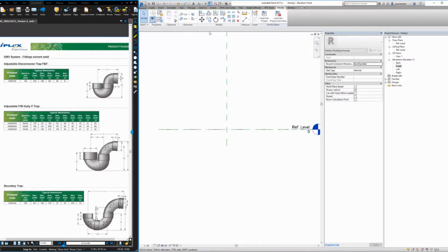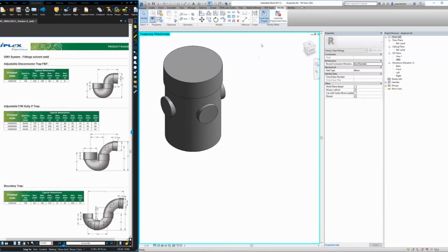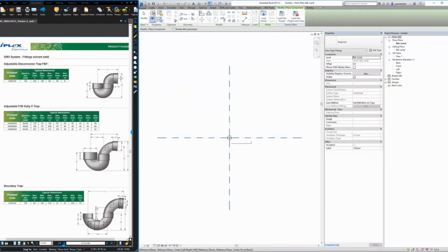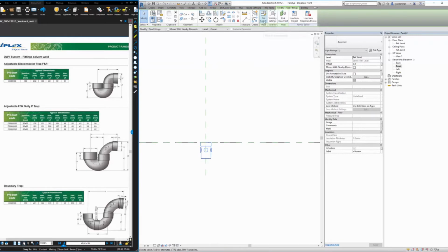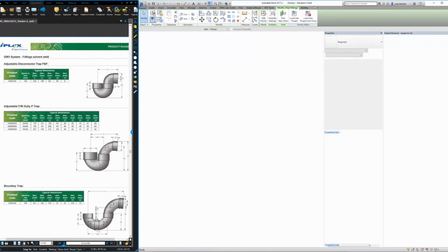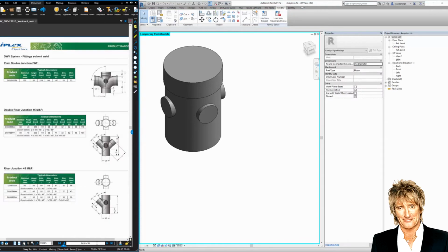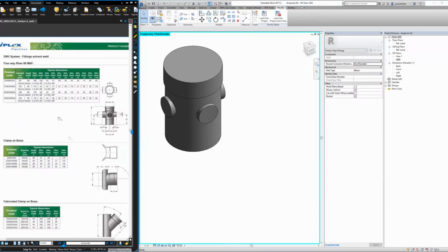So hydraulic designers out there would know that people stick weird things down drains. And one of the reasons why you want this 100mm trap is so things don't get blocked, and the plumber, if he needs to, can go out and stick his rod to clear out the line down the 100mm trap.